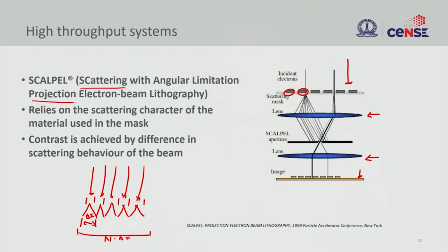So with that we come to the end of this lecture, where we elaborated on the resist process, and also how the energy is affecting your resolution through proximity and so on, and how to correct those. And also we saw an alternate form of illumination by using shaped beams, right, that is to improve your throughput and so on. And also you can use multi-beam as well, which is again an evolving technology.